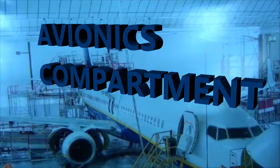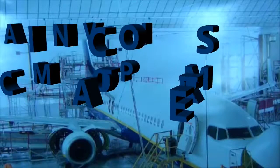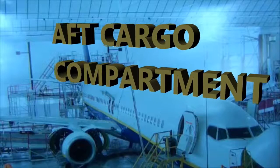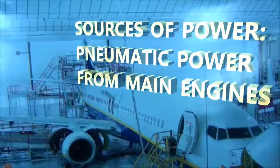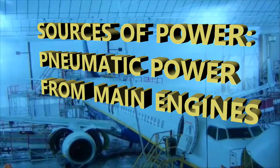And this is tied also with skin temperature, the airplane skin. So we're going to put that together with the avionics equipment, cooling, ventilation, etc. And then the other area that's affected is the aft cargo compartment, and there's also ventilation there as well as heating in that area. The source of power for the air conditioning system is the pneumatic sources from the main engines, the APU, and also high pressure ground supply.